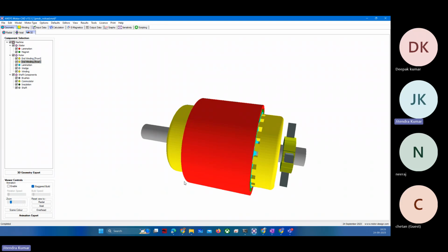You might have studied or will study in the synchronous machine section the winding factor terminology and the harmonics associated with those winding factors. So these distributions are basically sinusoidal kind of thing, but if you want to make a concentrated coil, then that will lead to certain harmonics in the machine.